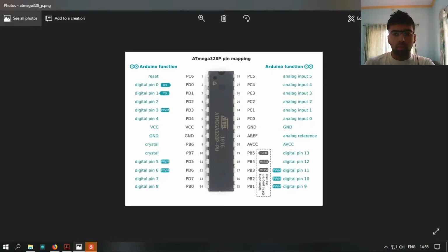Seems like my Atmel Studio has started. Before doing that, let's blink the LED on digital pin 13 of the Arduino, that is the pin PB5 of the ATmega328P, which is also the SCK pin in case of SPI communication, that is serial clock, which we will also be using, as the SPI interface, for programming our microcontroller.